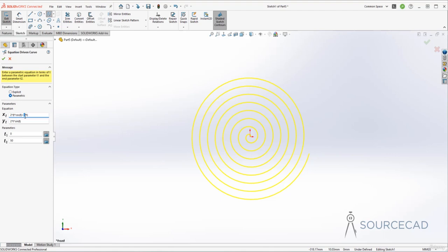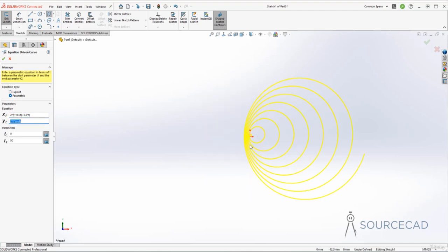Now let's change that to a Doppler spiral, where the focus is kind of shifted on one of the sides. And for that, you need to use a value that is close to 1 for this variable. So I'll just use 0.9, but not actually 1, simply 0.9. And now I'll press the Tab key. And here we are. So we now have this Doppler spiral at this place.